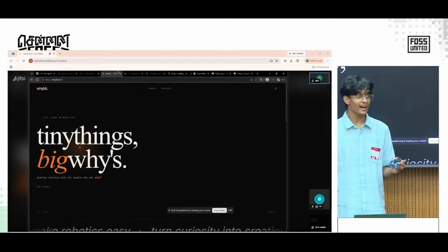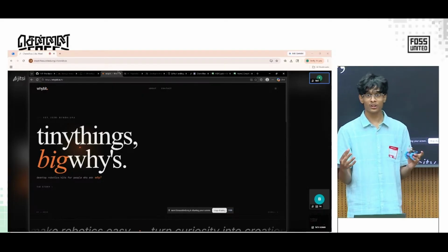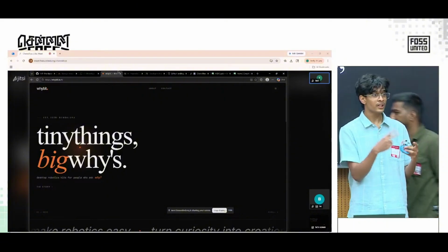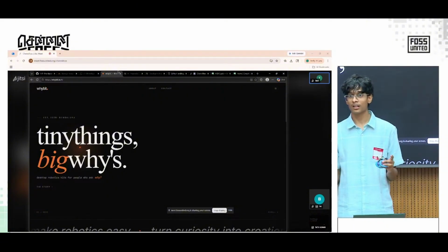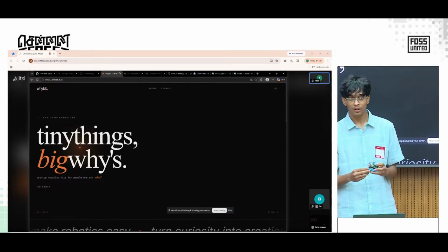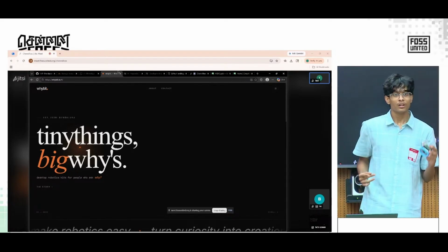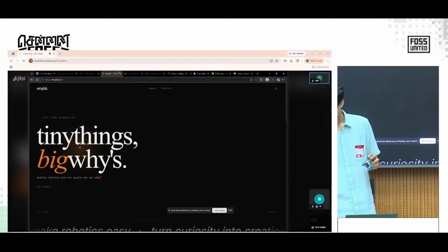So for that, I have to open up the servo motor, remove the connector to the potentiometer and convert it to 360 degrees. So now it is able to make a full 360 degree rotation. So that is the first problem which I solved.